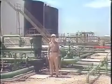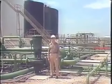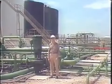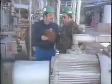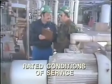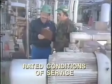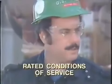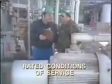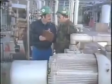Now, let's take a look at pump operation, startup, and shutdown. Centrifugal pumps are usually selected for a given flow capacity and total head, or pressure capacity, when operating at a given speed. These conditions are called the rated conditions of service, and are the conditions under which the pump should be operated for peak efficiency. If operated under conditions other than its rated conditions for long periods, the pump will be damaged and maintenance costs will rise.